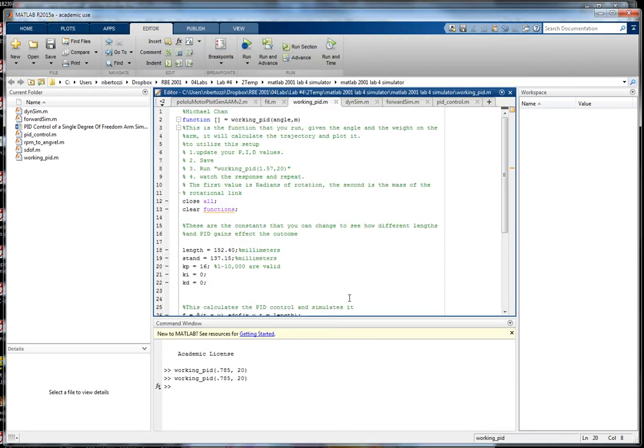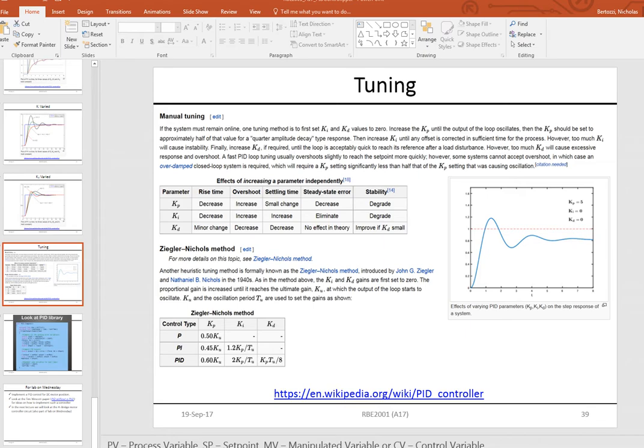This allows you to run this simulation and try to dial in the values for the gains. And remember from the lecture slides, we had these two different suggestions for manual tuning. So here's one procedure you can follow. The Ziegler-Nichols method, you can try and apply that. You can talk to the SAs and see what casual tuning technique they think will work.